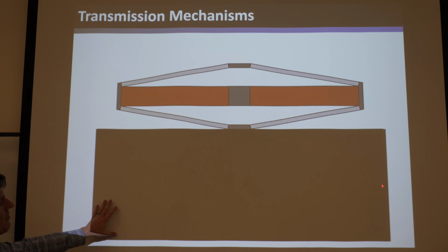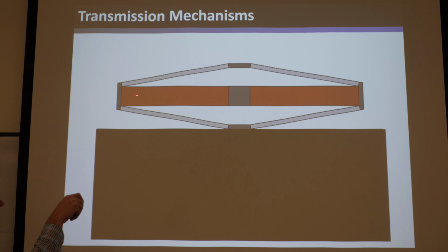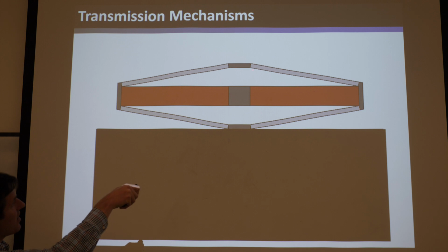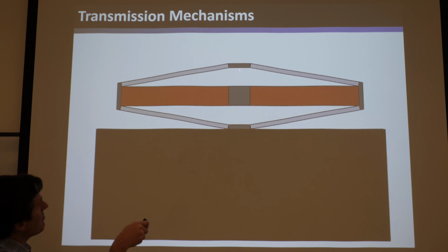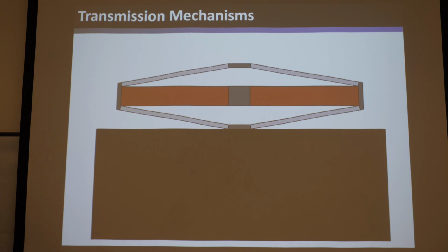So imagine this is just a big grounded body, and all this stuff in gray is a flexure, and this is like a piezo actuator. You can see it kind of forms a double triangle. Here's one triangle, and here's another triangle. If you've got an actuator that can expand or contract, and you put it in here, first of all, it changes the expansion and contraction along the horizontal direction to an output here in a vertical direction. But depending on the angle you have in these triangles, you can really ramp up with a double transmission. If this contracts a tiny amount, this can move a huge amount up. If it expands a tiny amount, it can move a huge amount down. And depending on the angle, you can tune that. If you have something that moves a lot, you can actually get this to move less, but with much more force. It's kind of a double transmission packaging. So transmissions are really useful, is the bottom line.